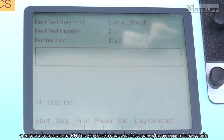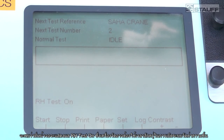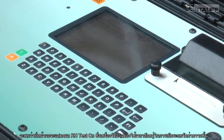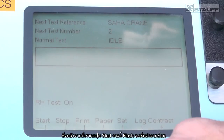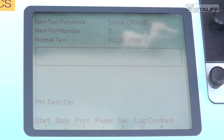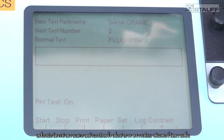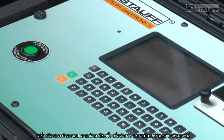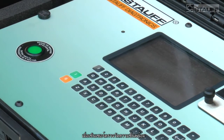When we take the moisture sensor test, it actually takes a little bit of time for the sensor to adjust itself, so it needs to calibrate itself. So it takes a couple of minutes before the actual test commences. So once we press start, the flash valve will come on and the particle counter will be flashing the fluid until the moisture sensor has been calibrated and it's ready to take the test.